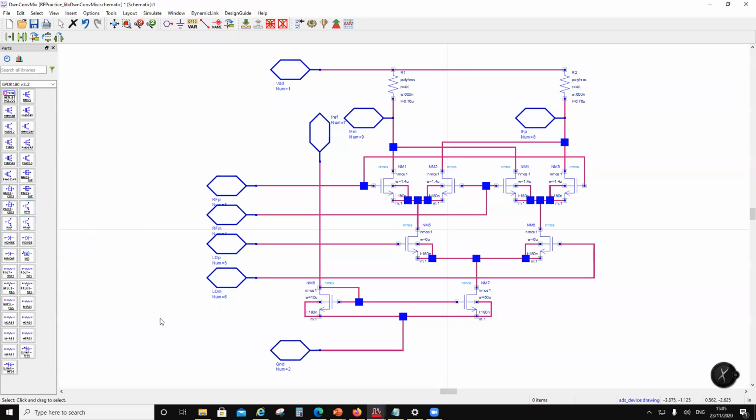So what I'm saying is, I can share this PDK, but expect to use only NMOS, PMOS, inductor, capacitor, and resistor. Don't use varactors, because these varactors are very crappy, very bad. I have only worked with NMOS, PMOS, inductors, capacitors, and these resistors.